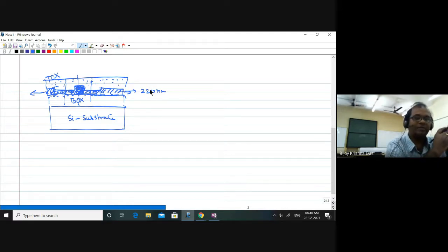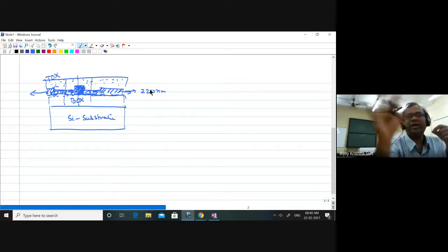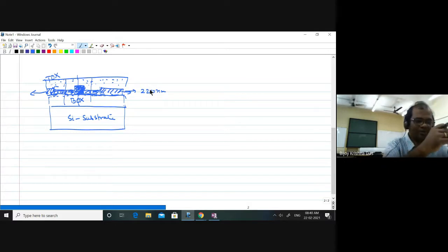So that is why it is a very challenging task to maintain the cross section throughout the waveguide length, which is less of a problem for your electronic wire transmission line. There you can manage; you can sharply bend an electrical wire, but a waveguide you cannot bend sharply. There you will see scattering losses, leaking of light. So those are the limitations there.